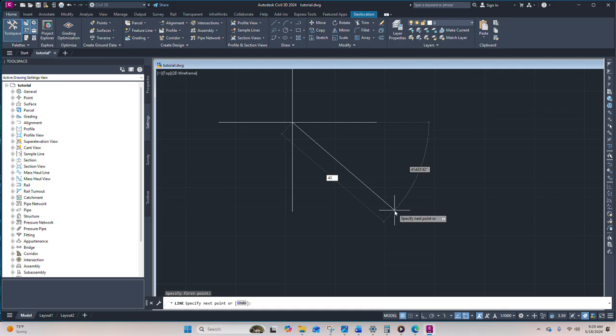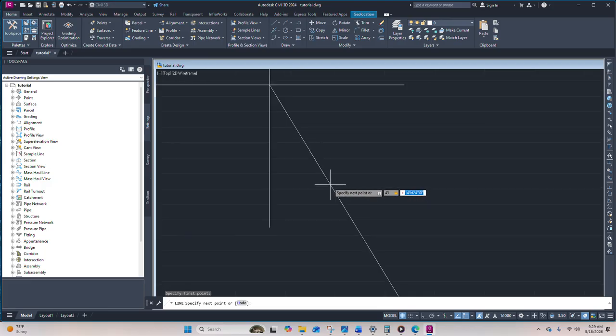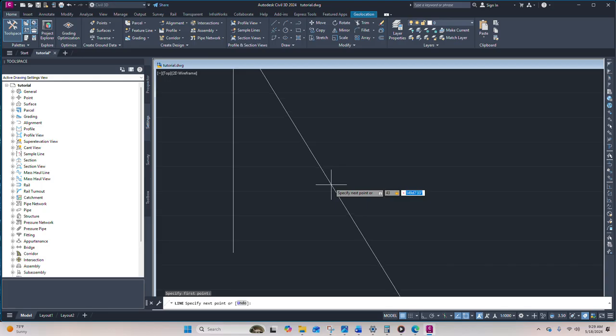Then from your keyboard, hit shift, then the angle sign. I think you call it the smaller than or the greater than sign. It's red in color. I hope you can see it clearly. 43, that's the distance. You don't input the units. The units are already in meters. So 43 at an angle of 289 D for degrees.